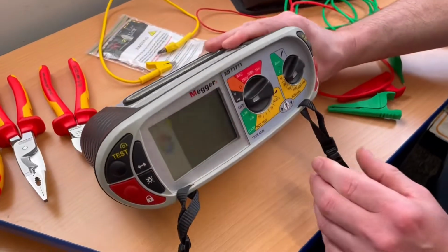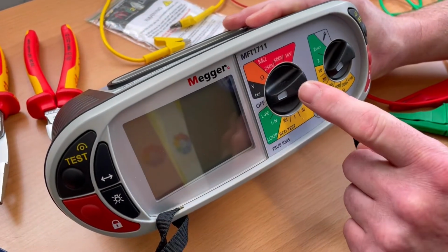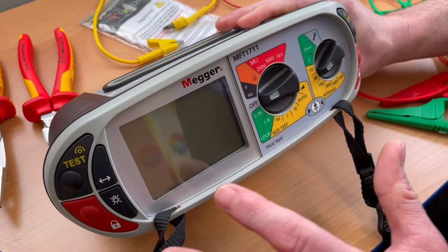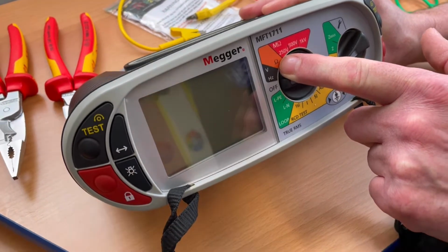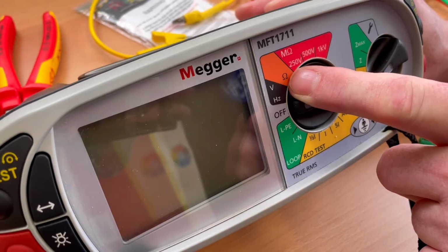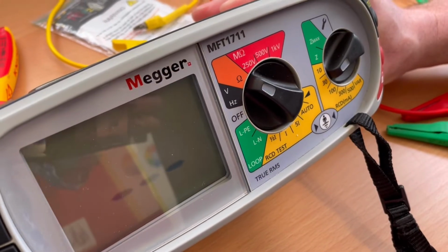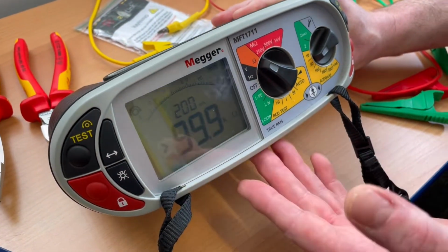So we've got a multi-function tester, we've got our Megger 1711, and we're going to be measuring the resistance of the circuit during that continuity test. So if you've got a slightly different tester than me, you're still looking for the omega symbol or ohms, and that's a scale we need to set it on in order that we can measure the continuity or the resistance of a conductor. So if I rotate that round, we'll see our machine comes on, and it's a case then of sorting out our leads next.